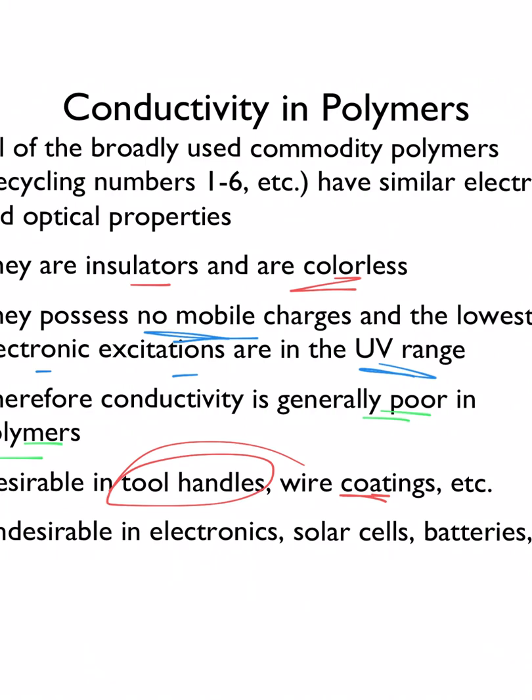I certainly didn't ask him to do anything. And so he had a screwdriver, yellow handle, and he took the panel off, and he went to touch something, and the electricity arced from the conductor to the screwdriver over to the ground, all right? And fortunately, he walked away. Now, by all means, he should have been blown across the room and maybe not be alive.